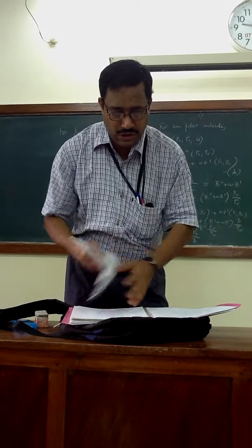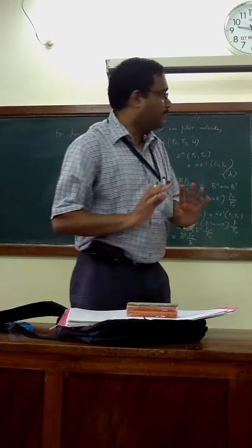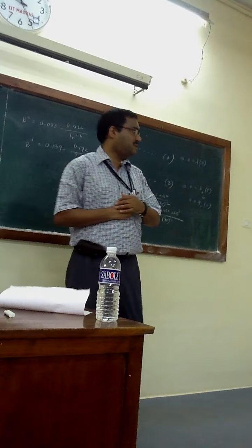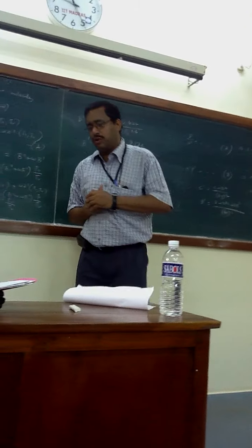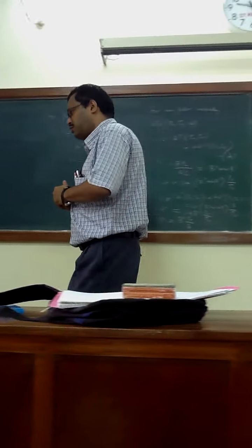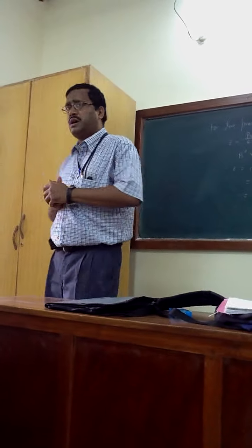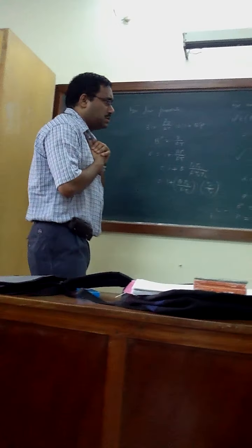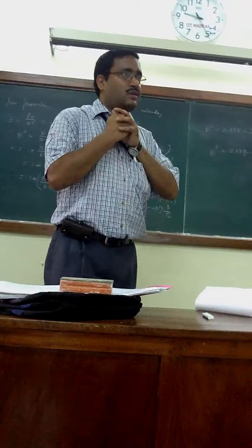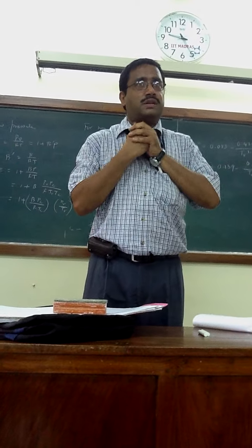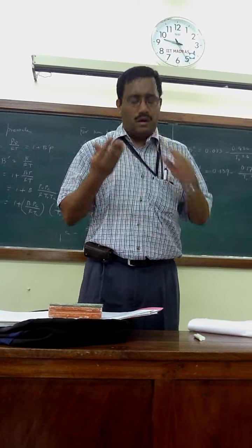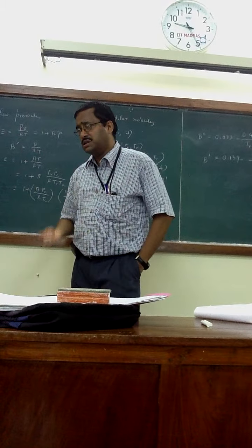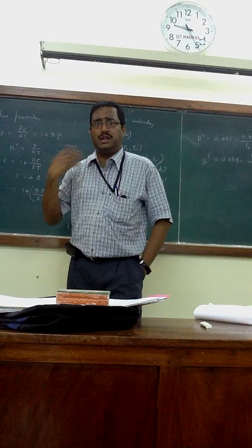So equation of state is done. With this much knowledge of equation of state, it is a big topic. There is still a lot of research going on. People are still working on equations of state and developing them for different kinds of materials. There are still a lot of materials in this world where we don't know which equation of state applies. Even if you employ your regular Peng-Robinson, SRK, whatever, even second class or third class, you cannot predict the behavior.